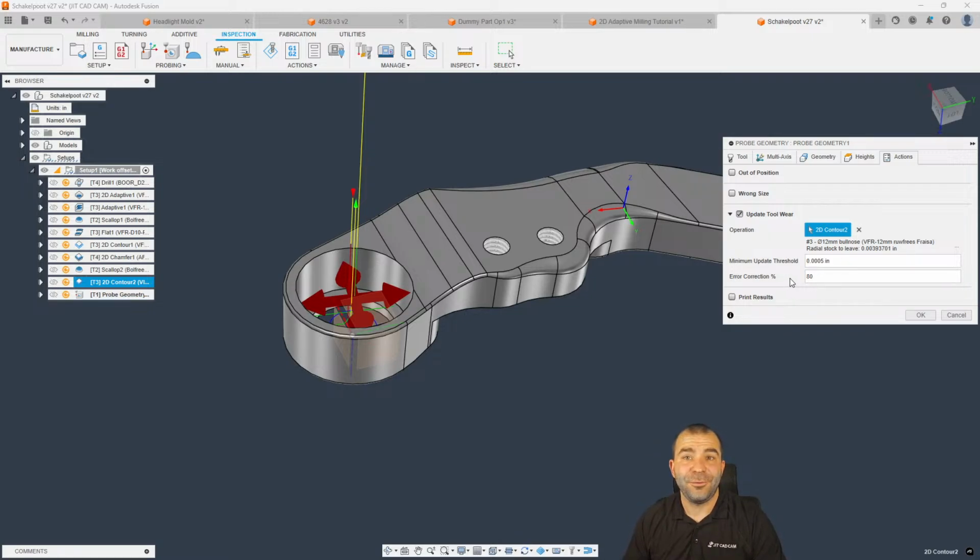So once we get to 5/10, we're not going to go all the way back to 0. We're going to go back to about 1/10, right? Sometimes you can just get a weird spot in the material, and if you overcompensate, you shoot back the other way or overshoot your actual correction. So instead of trying to get it dead on, we could walk it back to that location and still keep us all within tolerance, right?